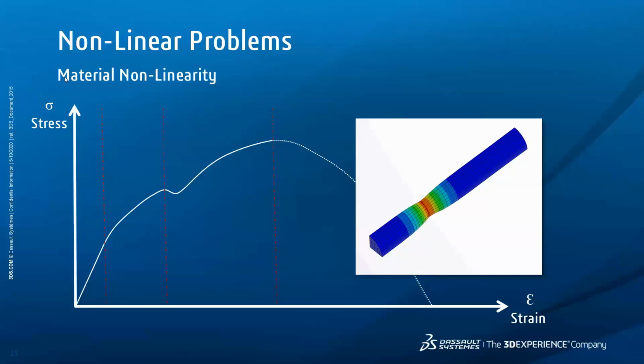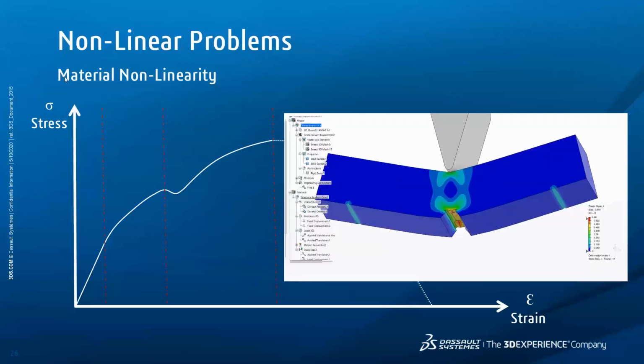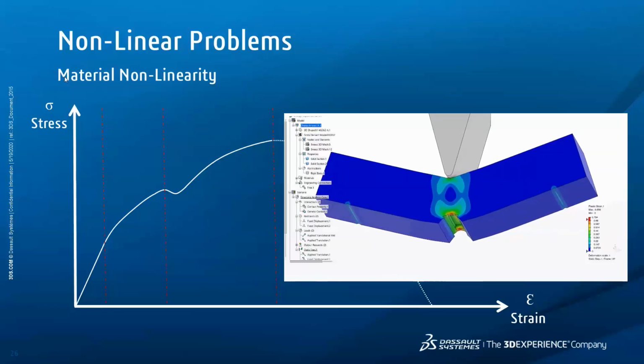For ductile materials, one method regards this onset of damage based on the nucleation, growth and converging of voids. There are others. The evolution of damage can then also be defined based on displacement or fracture energy, with softening options available. This allows us to visualize the destruction of products due to increasing loads and even ballistic impacts.